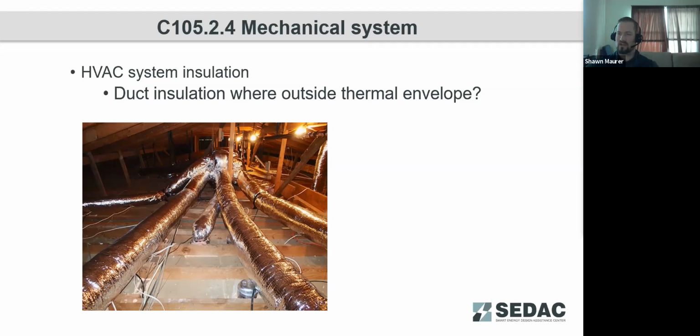Something to be aware of is if you've got ductwork above a drop tile ceiling, that ductwork is technically within a conditioned space. Drop tile ceiling plenum spaces are indirectly conditioned by the spaces that they sit above. So that ductwork is not required to have insulation, although we do recommend for designers that they include some there just as a protection against condensation should there be an envelope issue that allows moisture into that space. Since it's not being directly conditioned, it is more likely to develop humidity issues and then develop condensation on the ductwork.